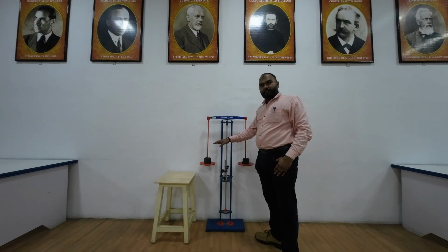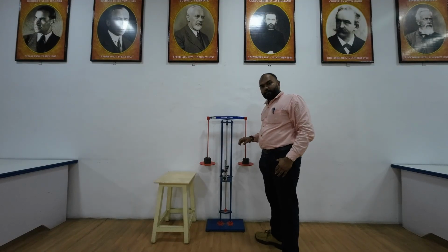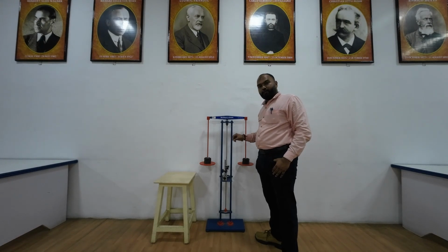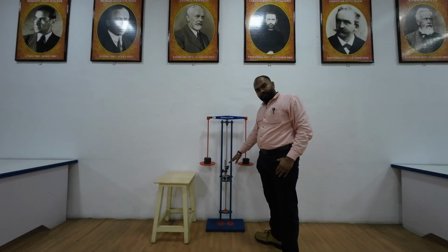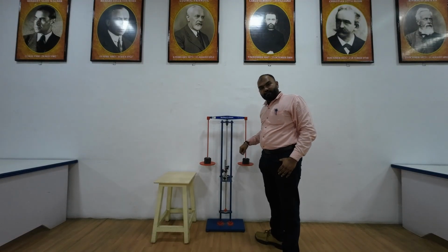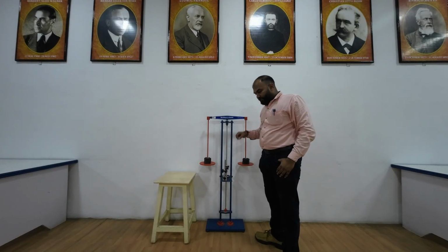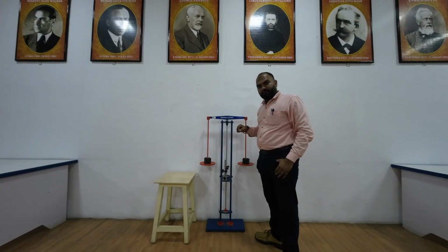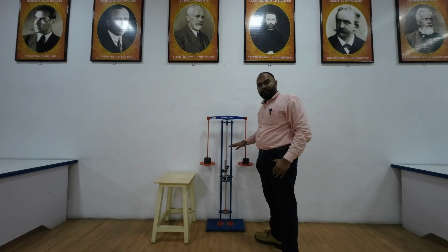Since we have measured delta and P, to find the buckling load or P critical, we will use the Southwell plot, which is the deflection measured from the dial gauge divided by the applied load, versus the deflection. We will get a curve, and from the slope we will be able to find the P critical or buckling load for this column.